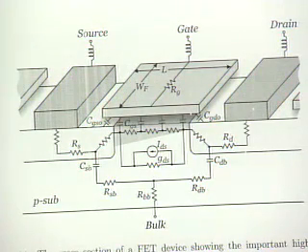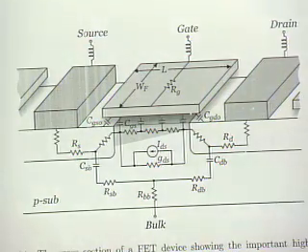how much power you can extract from a device, it all comes down to the losses in the device. I mean, partly it's the omega T of the device, right? We saw that even in the simple amplifier. But the other terms really came out to depend on the inherent resistances in the device. So if we can minimize these resistances in the device, we can maximize how much power gain we can get out of the device. So for instance, what are those resistances?